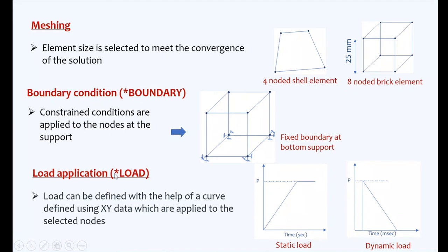Next is load application. Load application we usually perform by defining a load curve, like you define how your loading is done for the time duration. So you provide X and Y data, where X will be your time and Y will be your load application. So here I have just shown two representations.